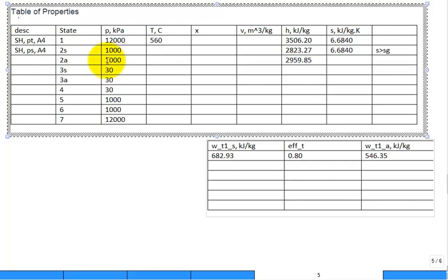Well, you can think that, hey, I have pressure and enthalpy. I'm still going to be in the superheated region, so I still use table A4 to look up any other property that I need. I could do interpolation to get the temperature. I could do interpolation of specific volume, but I don't need it. The one property I do need is the entropy S, because that's what's going into the next turbine. So you do the interpolation, knowing pressure and enthalpy in the superheated table, to get S. That's 6.9558.